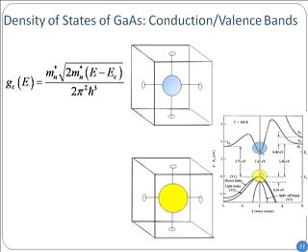Now, why is it called light hole, and why is the other called a heavy hole band? The reason is that if you have smaller curvature, second derivative of energy with respect to K, effective mass is inversely proportional to the curvature. Shallower the curvature, electrons don't want to go from one place to another, right? So in that case, you can see that the light hole and heavy hole bands have slightly different curvature, and therefore slightly different effective masses. You can again see that this is approximately spherical, and actually one can prove that as well.